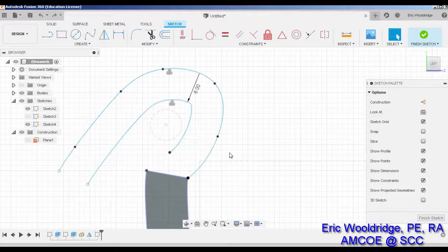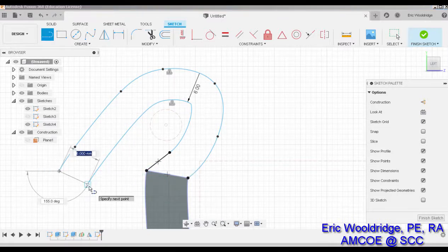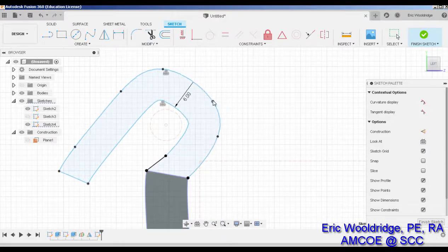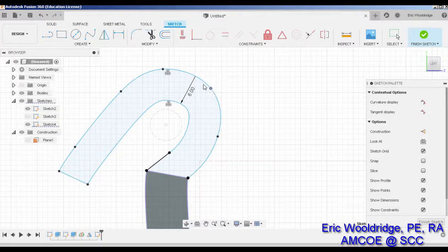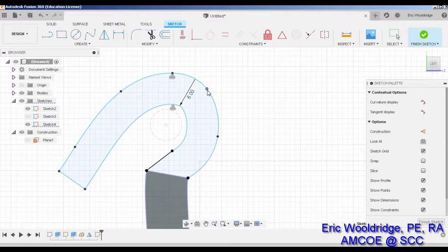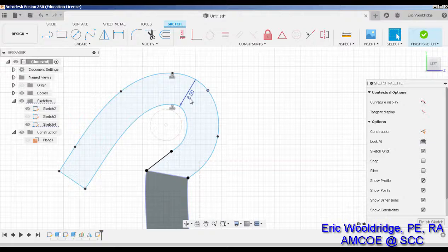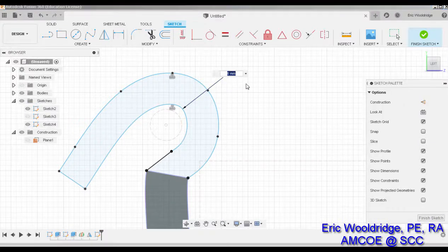No, it's going to do something funky there. So I'll just grab this line, click here, and there, close it off. And close that off there too. And as you can see, there's a lot of unnatural shaping going on. So I can grab these two grip points and reshape it a little bit better. We also don't really need this thing to be a full 6 units in thickness because it's going to be a solid, it won't be latticed. So I hit 5.